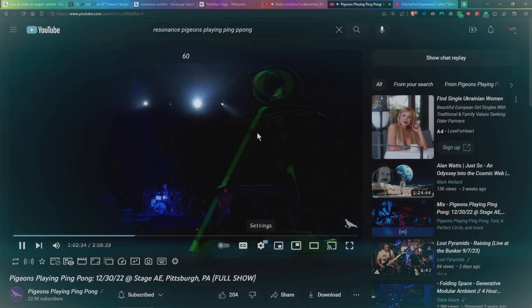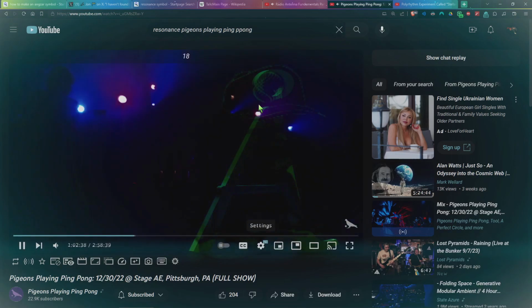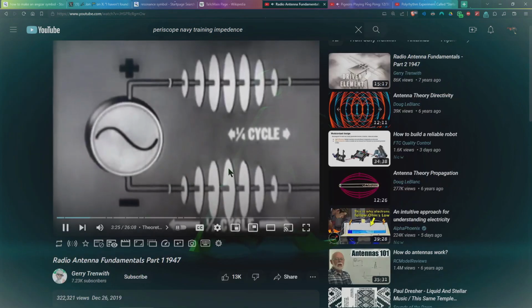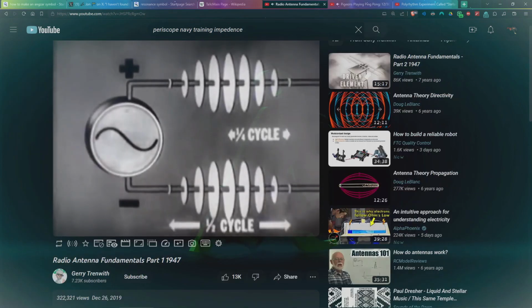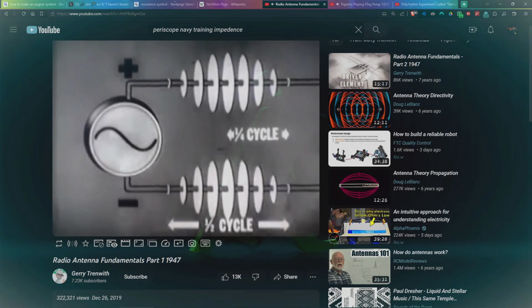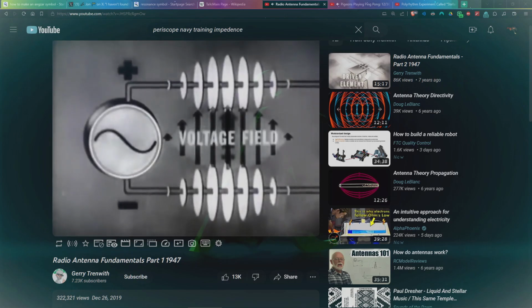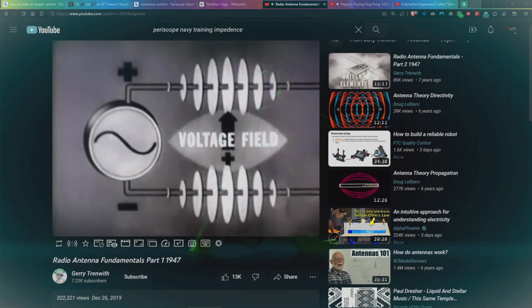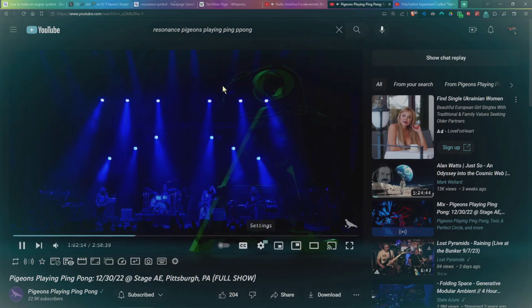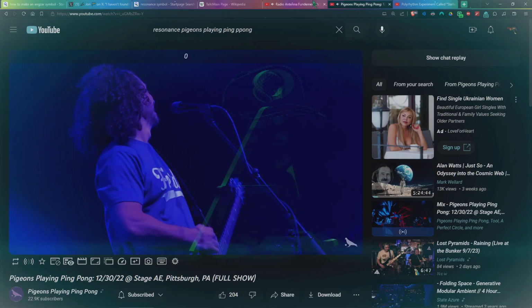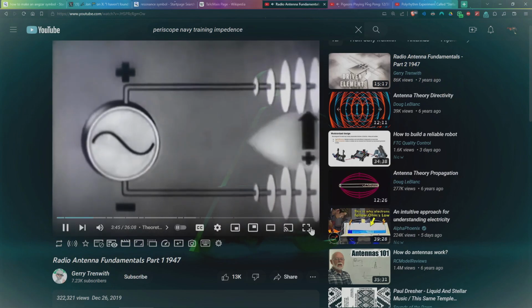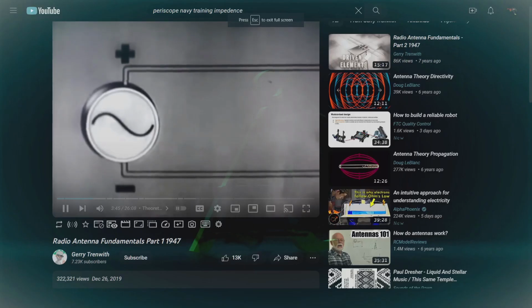Maximum magnetic field is produced at the quarter cycle point, because it is here that the generator is cutting the greatest number of flux lines. As in our demonstration with direct current, the magnetic fields cause this portion of the line to be charged to the voltage of the generator. Now let's continue the slow motion action to see what happens to this electrical charge on the wires. Even with the generator stopped, this single charge proceeds down the transmission line.